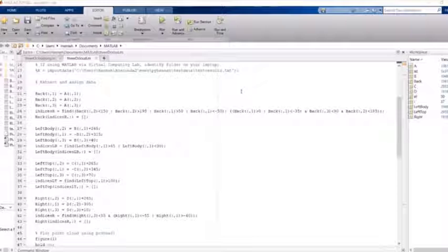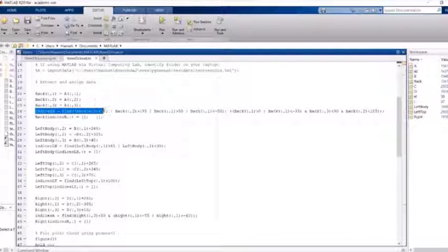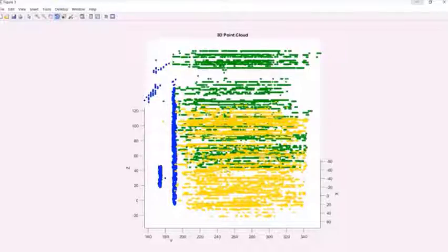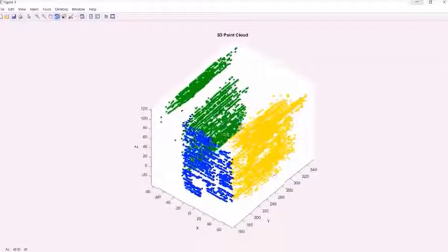Each point cloud contained erroneous points in front of and behind the wall faces. So I indexed these points in these areas that lay below the overhang and removed them. For the back face point cloud, I had to make sure not to remove the points showing the AC unit, so I removed this area from my indexing. Filtering in MATLAB resulted in this point cloud.